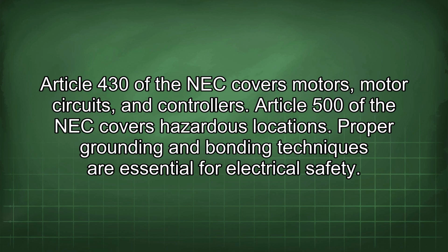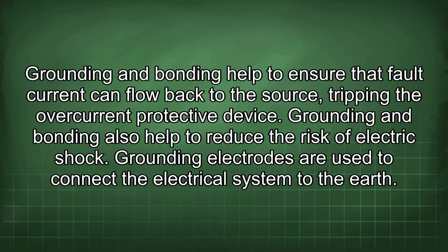Proper grounding and bonding techniques are essential for electrical safety. Grounding and bonding help to ensure that fault current can flow back to the source, tripping the overcurrent protective device. Grounding and bonding also help to reduce the risk of electric shock.